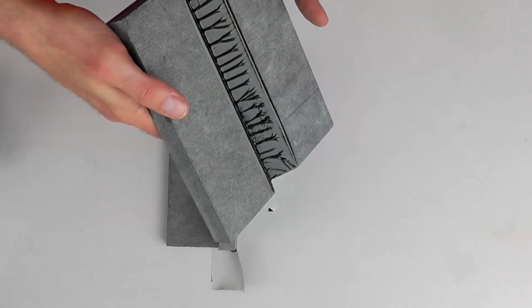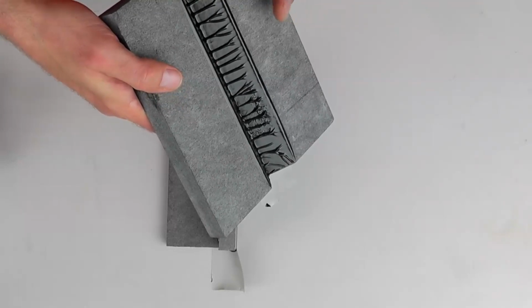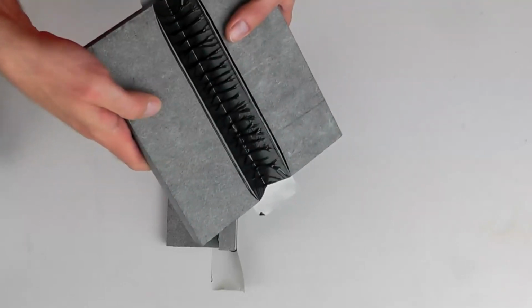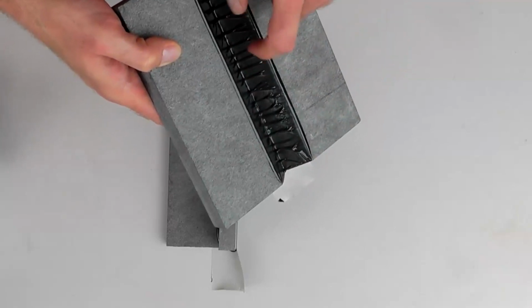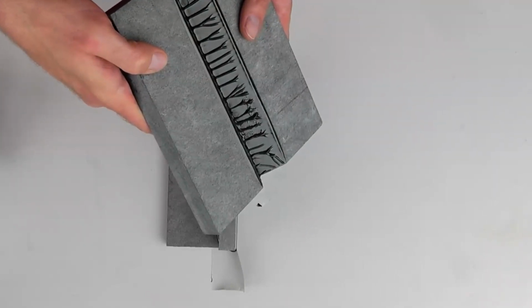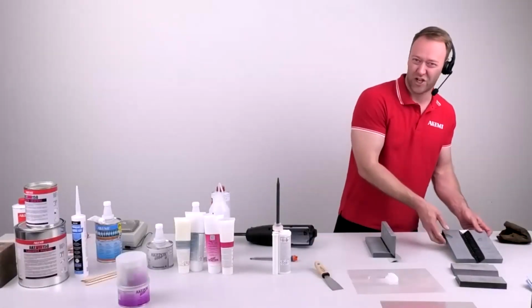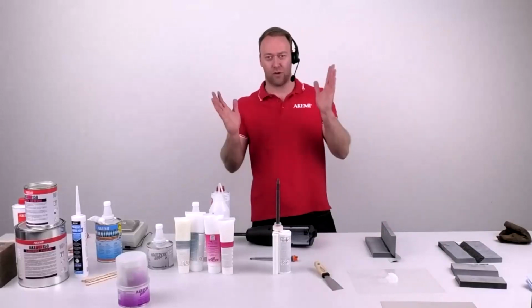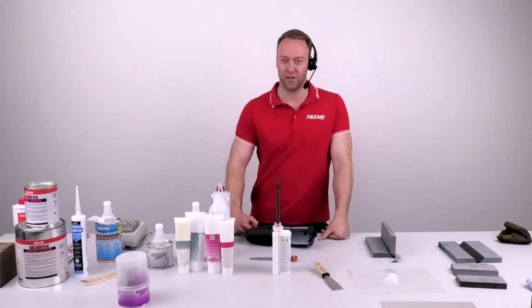These are the air channels or cavities you pull with the vacuum into your bonding. Up, open, close, open, close. Now it's cured, but this will also be in your bonding. So don't open and close your bonding. Measure properly, adjust properly, and press it together one time. Then you will have no issues there.